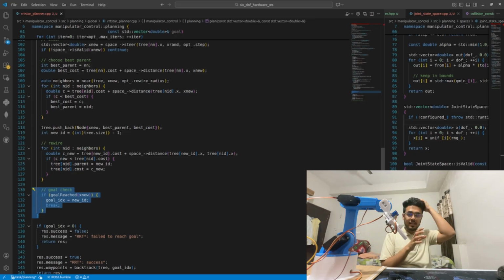But can I directly give that plan to my robot? No, these are servo motors. I have to make a pipeline for it. RRT star will give me some points. Now I have to interpolate those points to get a continuous spline in the real world. I will either make a line joining all those points, or I will make a cubic or quintic spline over there. Then this is the path.